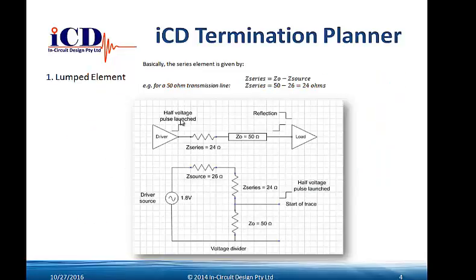So it's good to have, but if you have a long data bus, for instance, you still may require series termination. Now, series termination, if we looked at the basic lumped element sort of network, you can see we have a driver here which has a series terminator. The driver also has a source impedance and a voltage driver source. That goes into a series terminator and into the, say, 50 ohm transmission line, and then into the high input impedance load. Now, this is a basic voltage divider.